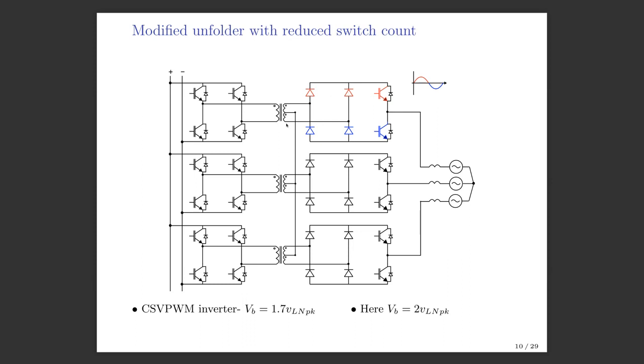And you can see here what we are doing. We have now 2 windings. So if you know a little bit of power electronics, this is the famous push-pull configuration. So when you are in the positive half or in the red part of the grid line, then you will be basically rectifying with these 2 diodes and this switch will be on. And when you are in the negative half, then these blue devices will be working. And again, these half bridges are line frequency switched, incurring very limited loss. And the diodes are basically doing the rectification here.